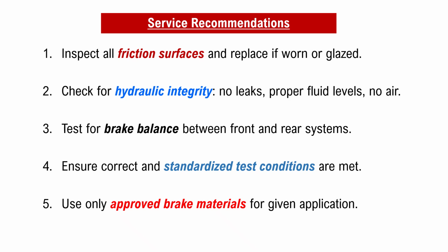Here are some recommendations related to service. Inspect all friction surfaces and replace if worn or glazed. Check for hydraulic integrity, no leaks, proper fluid levels, and ensure that there is no air. Test for brake balance between front and rear systems. Ensure that correct and standardized test conditions are met. And use only approved brake materials for the given applications.